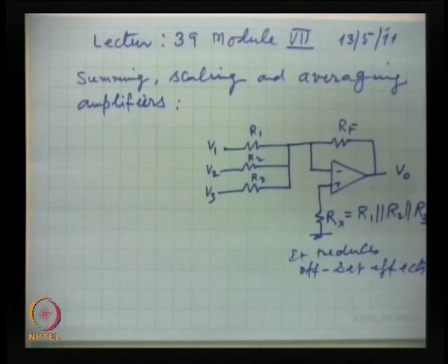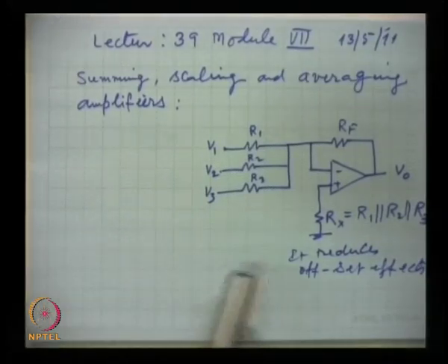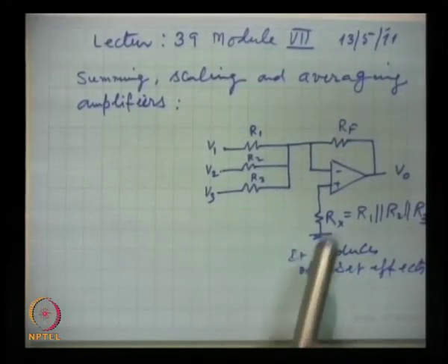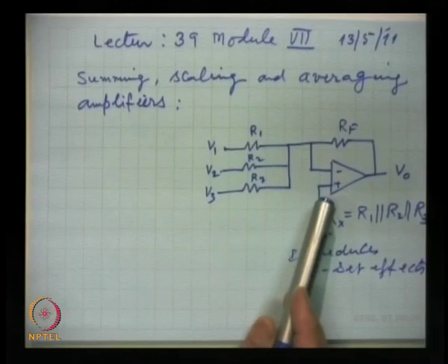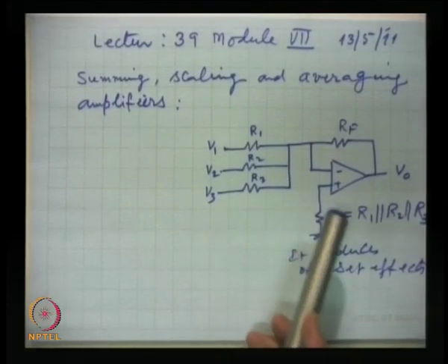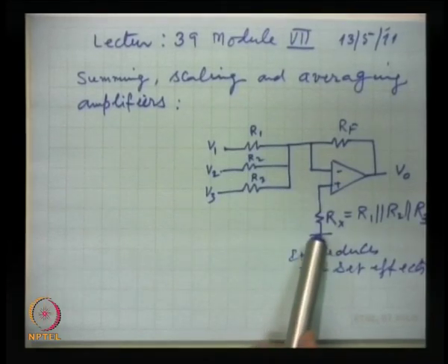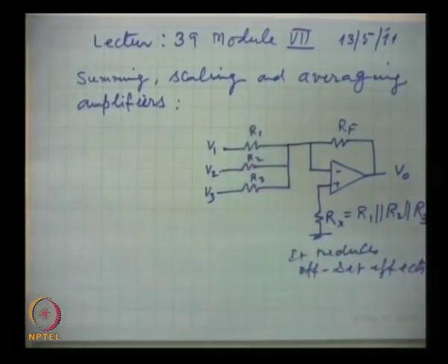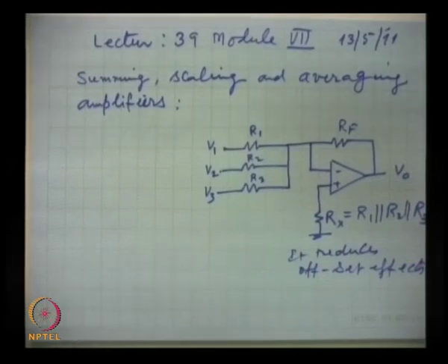They are of course very mild, very small currents, but still. Those offset effects can be reduced drastically if, instead of directly connecting the non-inverting input to ground, it is connected through a resistance equal to the parallel combination of all the input resistances.